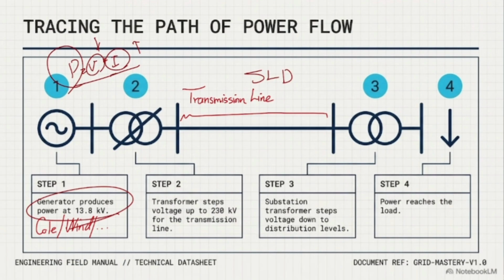Having high amounts of current means that in the line between the generation part and the distribution part, or just the load part, we are going to have a high amount of current, and at that point we have R I squared. Why are we talking about that? Because a transmission line or any cable or wire has resistance. If you have resistance, which is constant, but you have a high amount of current, you have a higher amount of power loss, because power loss has a relationship with the square of the current itself. And at the end of the day, you're going to have lots and lots of heat. That's why we use the step-up transformer.